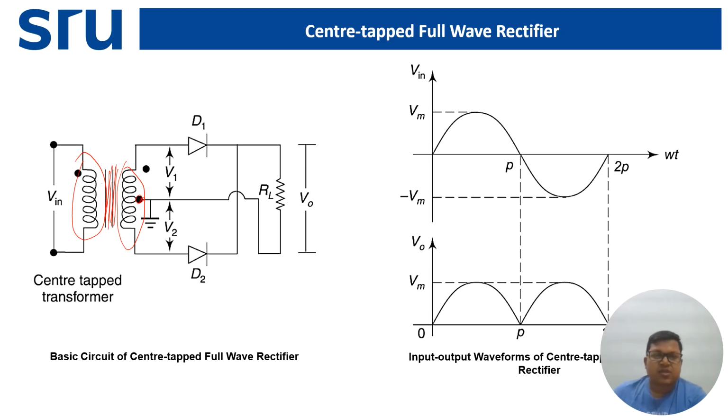That means the voltage coming across this secondary coil comes as half positive on this side and half negative on this side. If it is 9 volt, this side is 9 volt and this side is again 9 volt, so it will be a total of 18 volt. Okay, forget about that. Let's now continue our discussion so that we see the output as AC converted into DC.